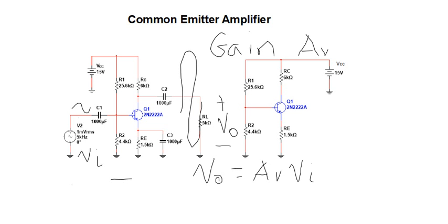Now, if I set this amplifier up in a laboratory, or if I do it on Multisim, I can measure Vout and I can measure Vin, and I can define the gain in terms of those voltages. And just divide both sides by Vin. So I can measure that gain that way, measure Vout and Vin, divide them together.